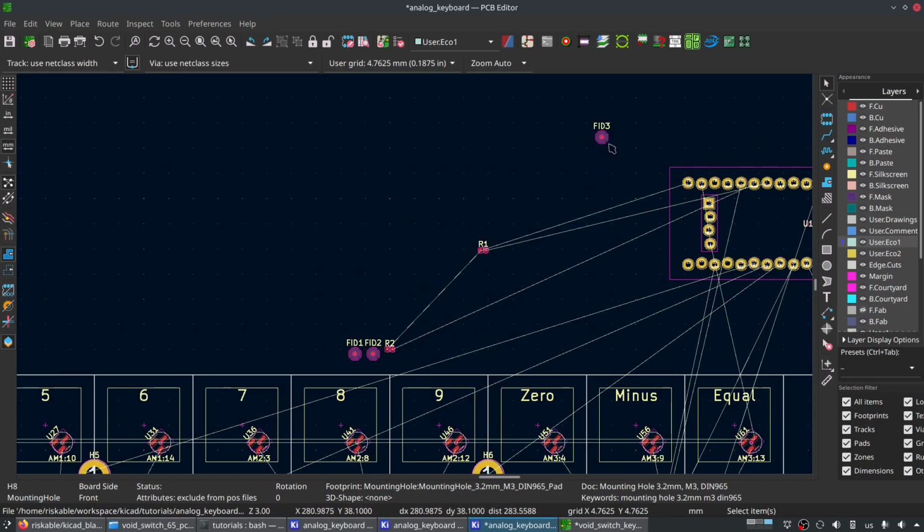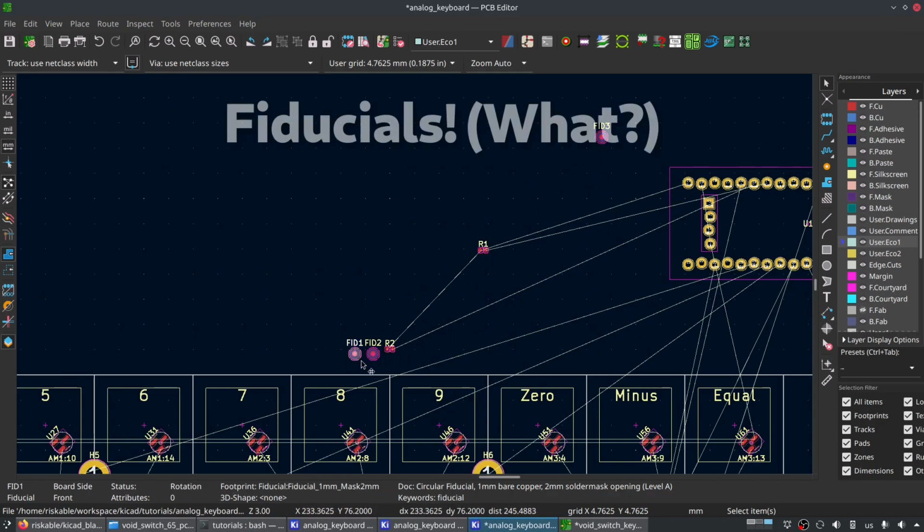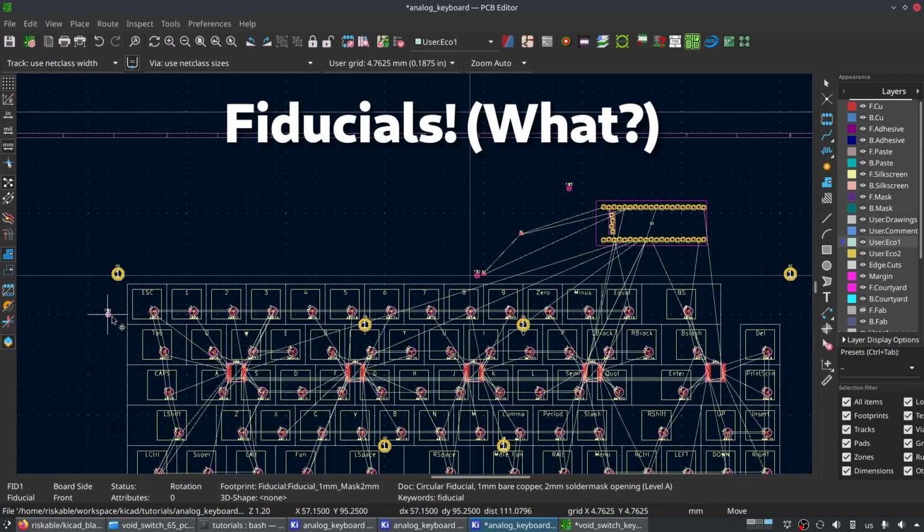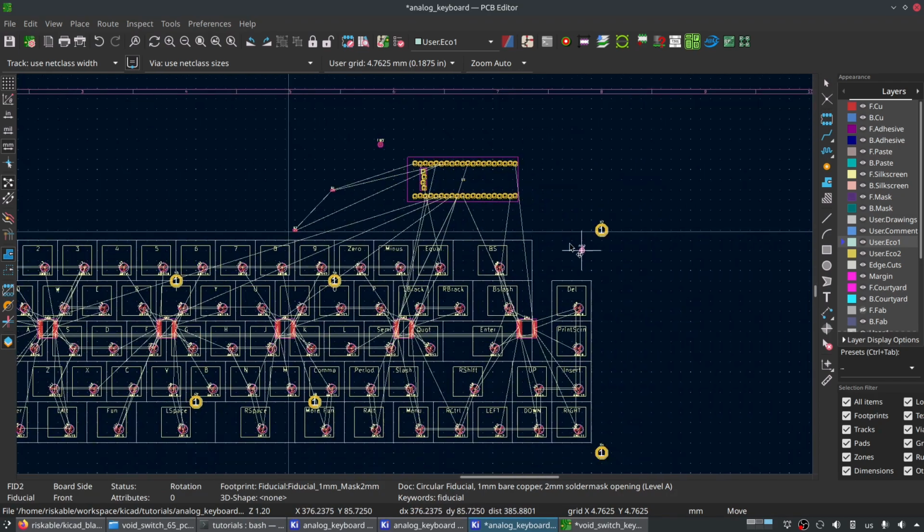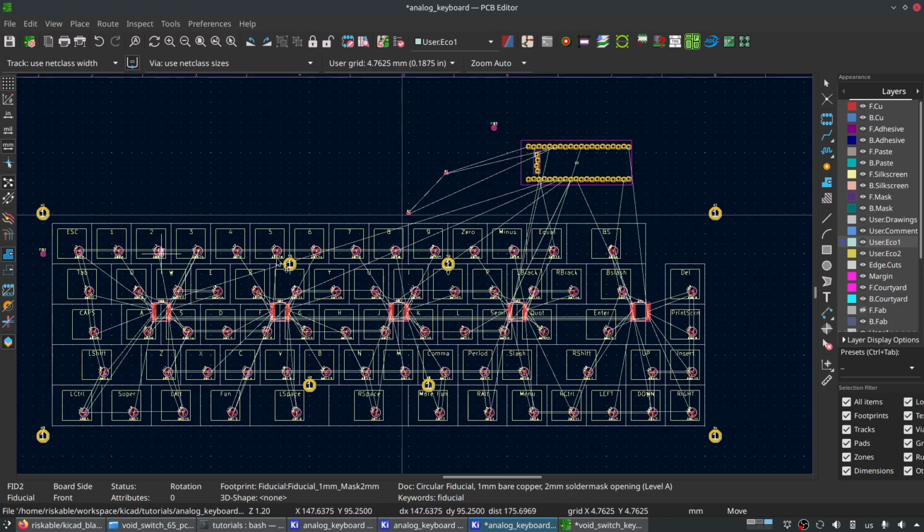Now we can draw the outline of our board. But before we do that, let's move these fiducials. Just put them over here somewhere, like line that up there. And one mistake would be to put it exactly in the same spot on this side. We don't want to do that. So instead, we're going to put it right there. And for the bottom one, it doesn't matter, anywhere around here is fine. Just remember, you don't want it to be symmetrical. So we'll put it here. That way we can draw a triangle that's not perfectly symmetrical, but it covers the majority of our board.